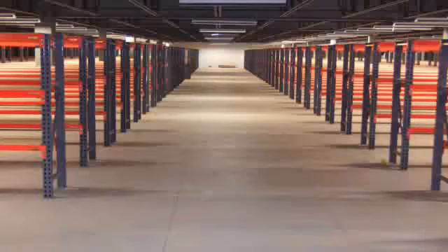For this type of rack, because your containers are so small, they're usually boxes or cartons or totes or something like that, there needs to be a decking material placed between the front and rear beams. This slide illustrates basically what you'd call an engineered wood product, but other ones used are wire decking, plywood, or even a solid or punch corrugated decking or other common decking materials for this type of rack.